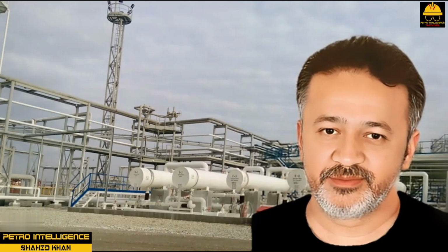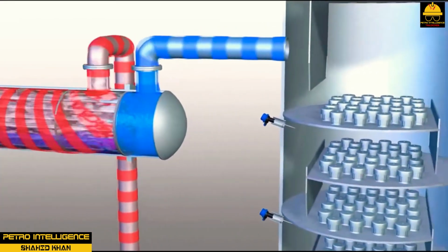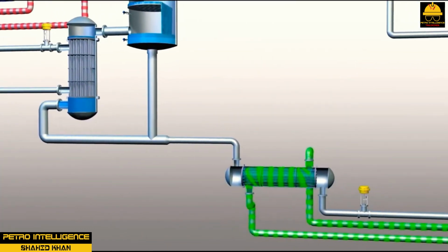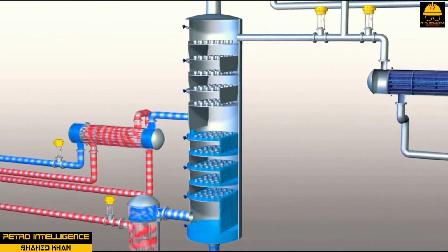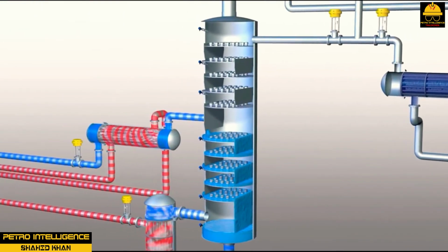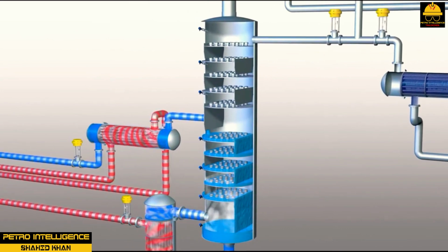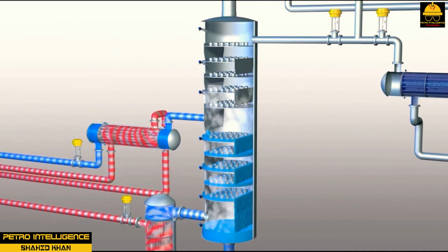Distillation columns. Distillation columns use heat exchangers to preheat feedstock in a heat exchanger, condense hot vapors in a condenser, or add heat to the tower and crack or separate heavier components in kettle and thermosiphon reboilers. Condensers are typically shell-and-tube heat exchangers used to condense hot vapors into liquid. A condenser can be found at the top of most distillation columns.